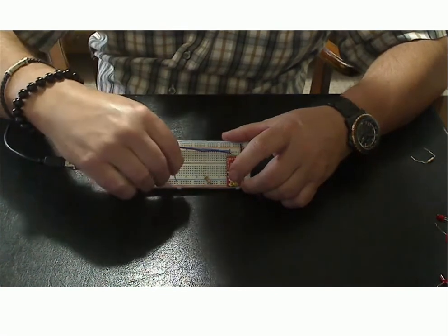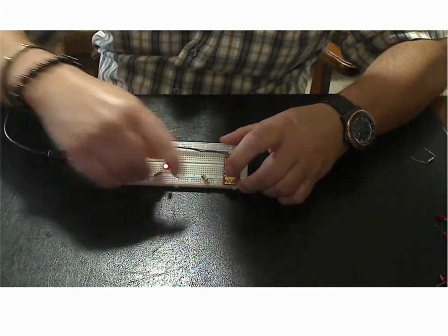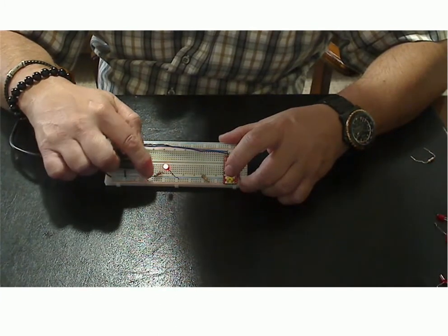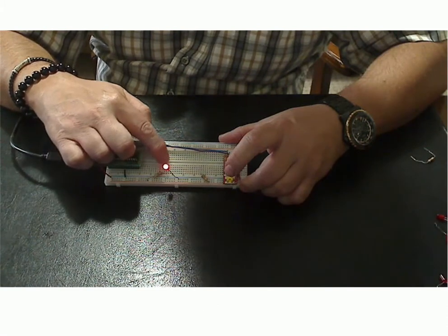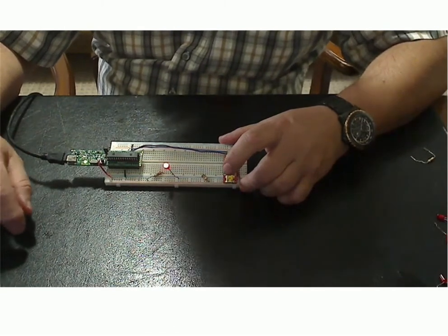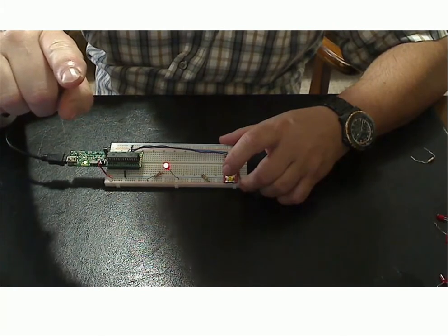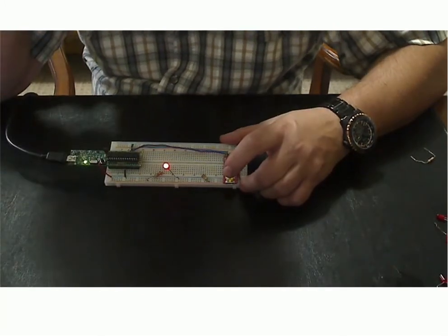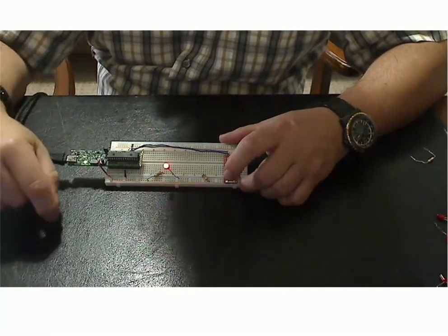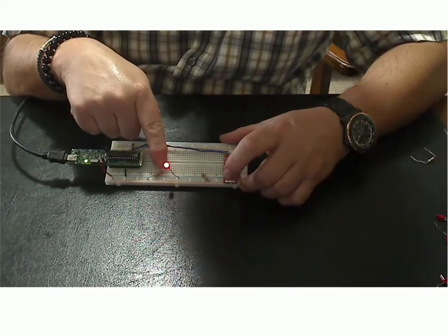What's the proper direction? Well, for an LED circuit, we're starting with high up here, 3.3 volts, going through a resistor, and then through the LED to ground. That's the type of circuit we're talking about. We talk about conventional current when we go from high to low. The electrons actually flow in the other direction. Okay, so I have this here, and what we've just learned is that LEDs are one-way devices.